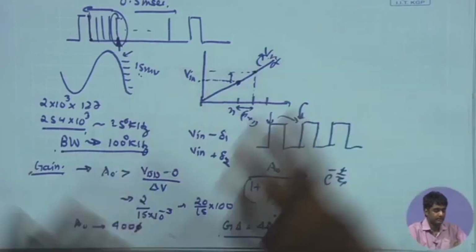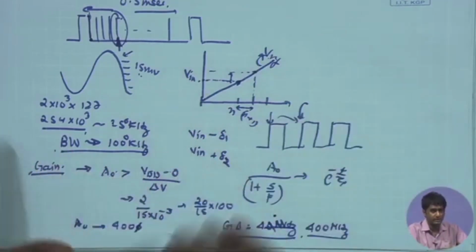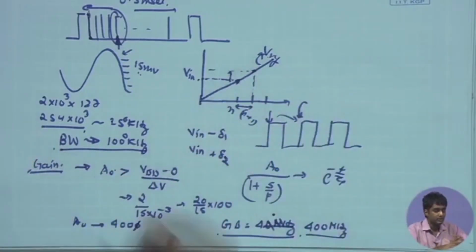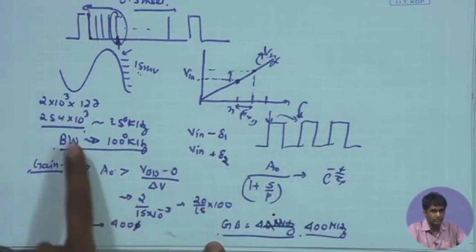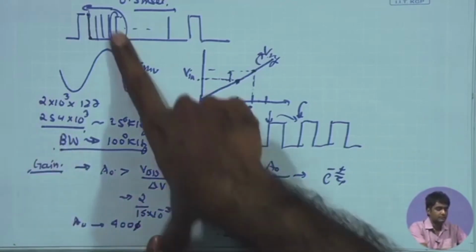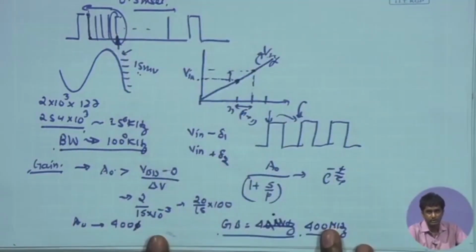So we can see that if you're trying to extract more information from the data and trying to have larger frequency content in the data, you are paying the cost in the analog domain. You are having to put more gain for the comparators, and the digital part, which is the clock and the control unit, is going to become more power hungry.